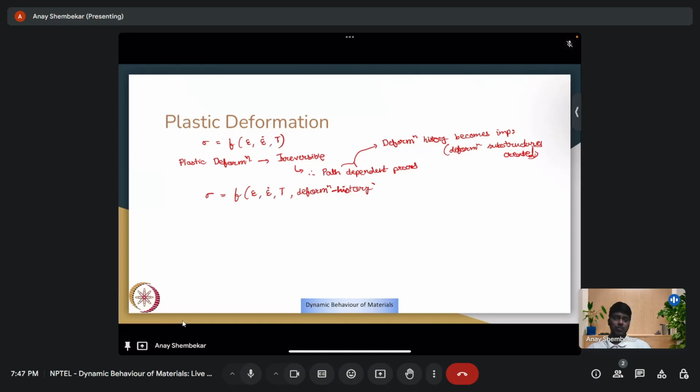Normally, those of you who have looked into solid mechanics or even done a strength of materials course must know that stress and strain in general are tensors. So what we mean here is we basically substitute stress or strain with their effective values, by constructing a scalar effective value for the stress as well as the strain using the principal values, so on the principal axis.